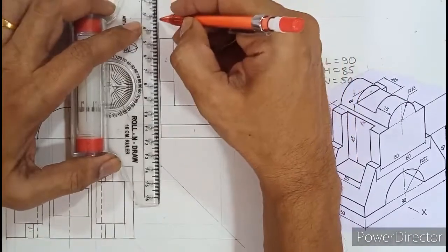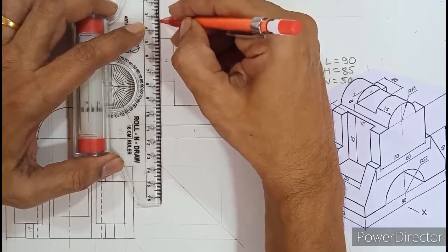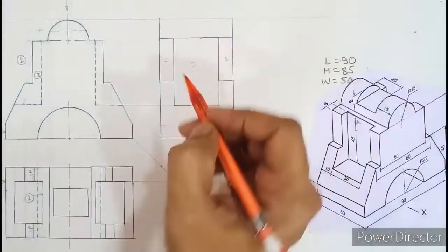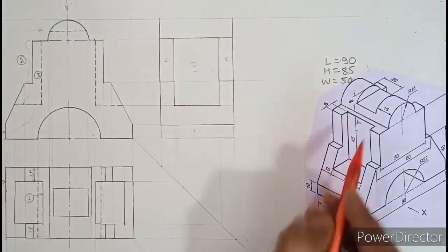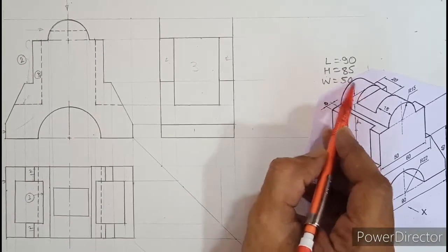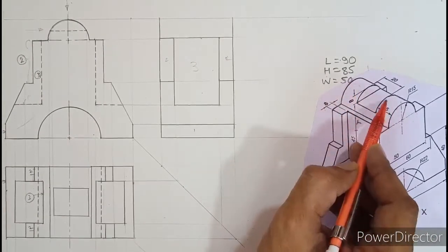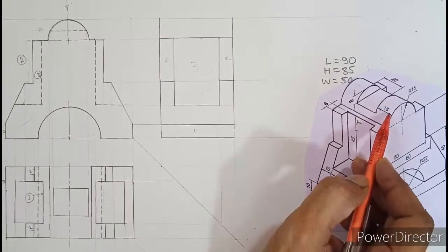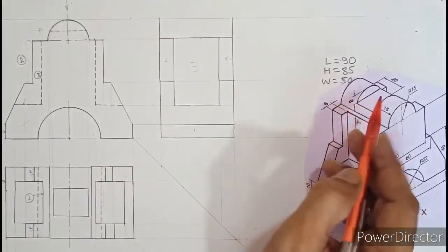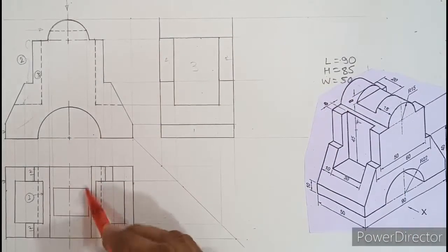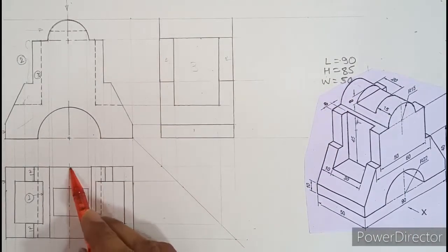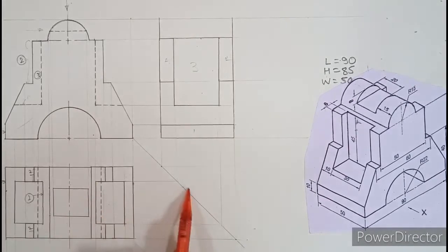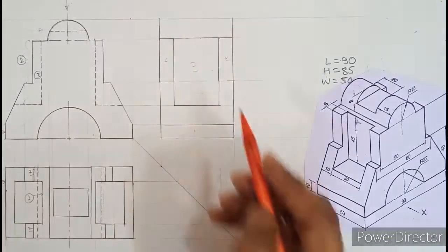For that we need to close this edge, and it lies on the extreme side because there is no object beyond that. So we have closed this on both the sides. Then, as we discussed before, you can see the boundary of the cylinder, which is 15 mm wide. There is no need to measure 15 because in the top view you have already drawn 15. In the top view, the cylinder is in the center, isn't it? This dimension is 15, and one more 15 is from the bottom. If I project both of these in the side view, I can easily get the cylinder.